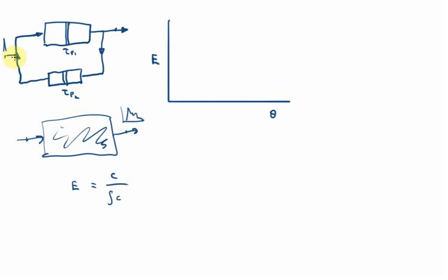So we can imagine we've put in this pulse here. It reaches this PFR, and of course we assume that this line is small enough that it offers a zero space-time. So pipelines are considered zero space-time zones. So here, after a period tau P1, we will have a contribution from here.